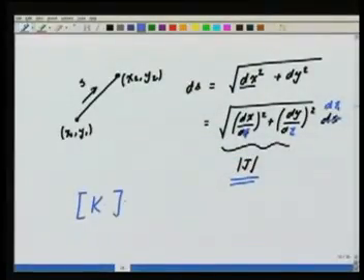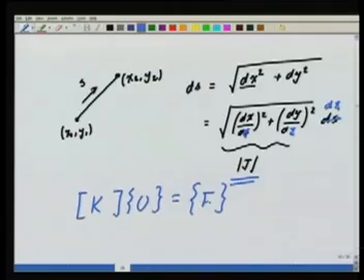So this way I can complete all my integrals that we have to do for the element, and given my local to global enumeration, I can assemble the stiffness and the load vector components into their respective global stiffness and global load vector entries, Ku = F, apply the essential boundary conditions by fixing those known degrees of freedom to the known values, and go ahead and solve. So I should be able to solve the complete problem.